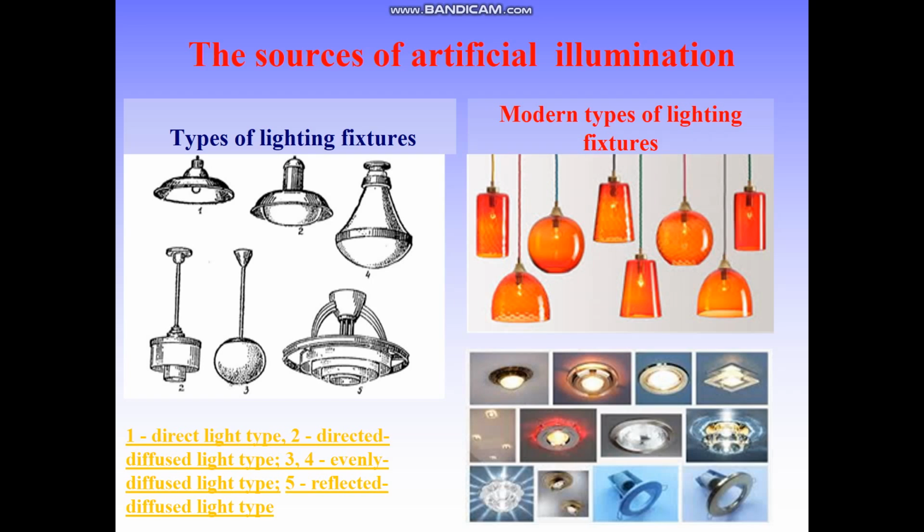Today, electrical lighting is mainly used because it provides sufficient and uniform lighting of premises without heat and byproducts of burning. The filament lamp is filled with inert gas, and the light energy is generated due to heat of the tungsten filament during the electric current passing through. In recent years, fluorescent lighting has become widespread, which is a matte glass tube with mercury fumes inside.